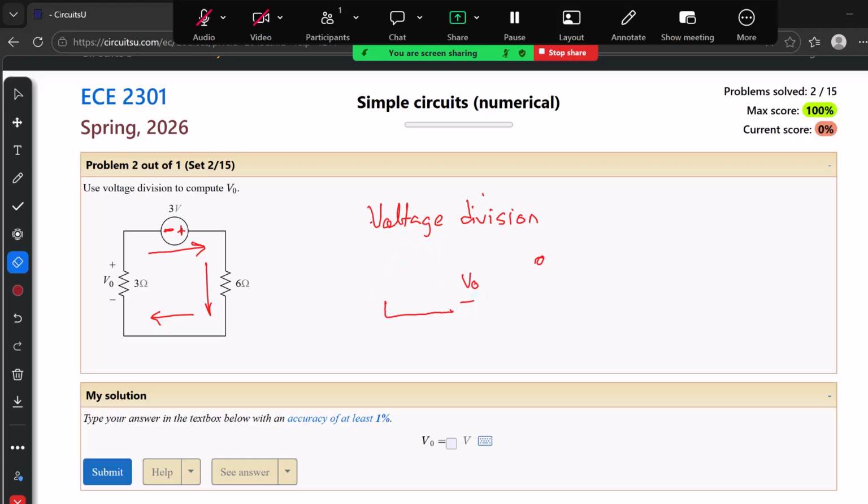So in this case, we will apply the formula. We know that this V naught is telling us that the result is going to be plus minus. However, notice that since the current flows clockwise, we will have the current entering the negative terminal. In this case, then, the voltage will be negative because it's entering the negative terminal that the answer asks us for, with the polarity of the voltage.